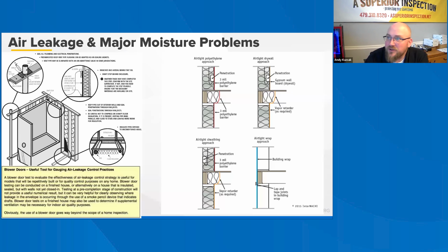In cold and very cold climates, the primary concern is preventing interior warm and humid air from flowing outward into the building's exterior envelope assemblies during winter months. This airflow can carry a large amount of moisture and cause condensation in the wall. Therefore, the use of an interior air barrier system in cold and very cold climates is preferred and may be combined with a warm-in-winter vapor retarder.